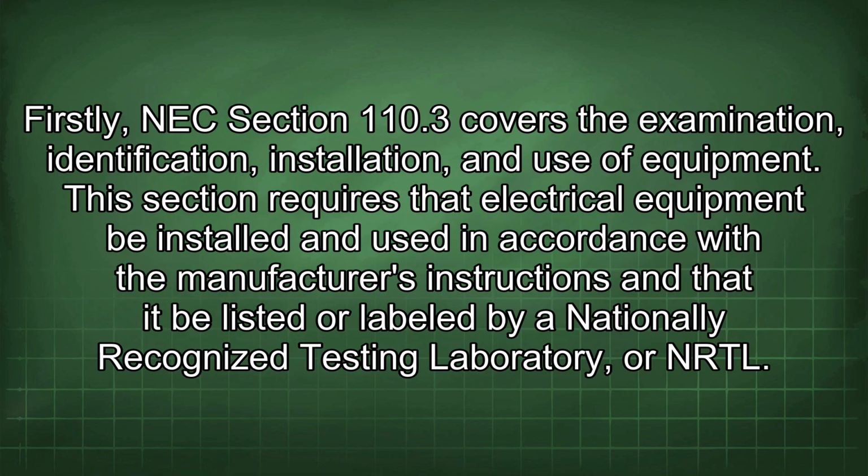Firstly, NEC Section 110.3 covers the examination, identification, installation, and use of equipment. This section requires that electrical equipment be installed and used in accordance with the manufacturer's instructions and that it be listed or labeled by a nationally recognized testing laboratory, or NRTL.